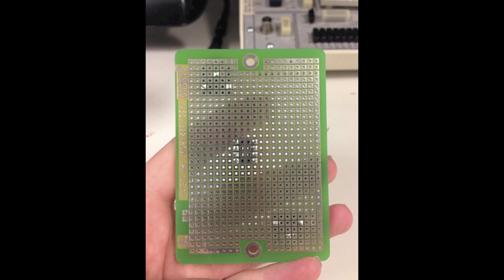And remember that you can always test your connections using the ohm meter, and there's even a cute little continuity setting where it'll beep when things are connected. So keep this in mind as you're soldering, so you can test to make sure that your solder connections are good and that things aren't soldered together that shouldn't be. The other thing to notice is that the metal pads on the board are only on one side of the board. So when you're soldering, make sure that the soldering is happening on the side of the board where the metal pad is located. Don't try to solder to the plastic on the back of the board. This will just melt the board and smell funny and not really work too well. So just keep that in mind while you're working on things.